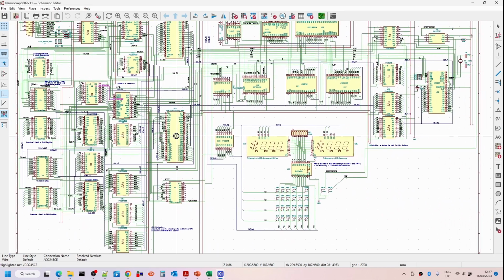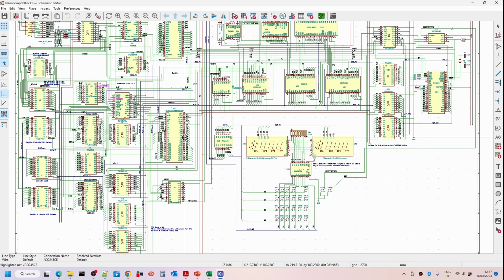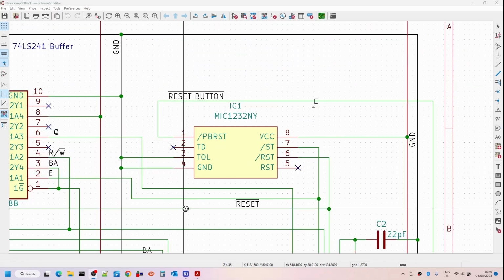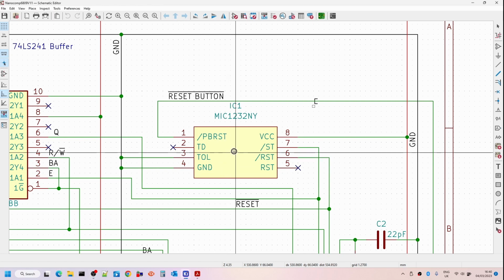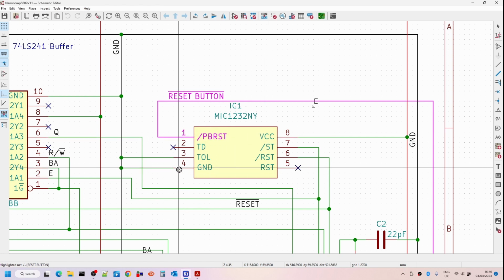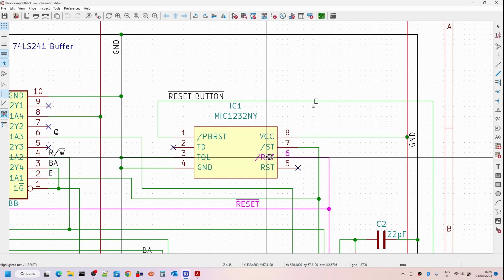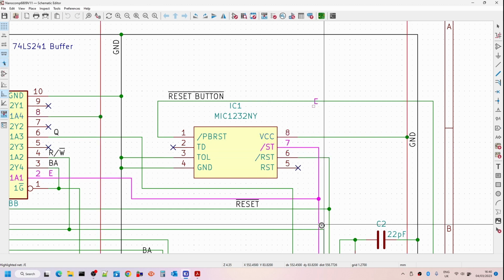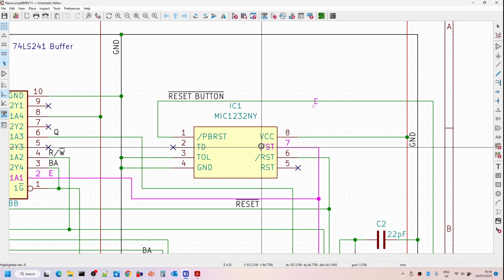So those are the changes. What I'm going to do now is to go in and look at the board layout and the wiring of this up, and then we'll come back and look at the software that we need to drive this. We're first going to install the microprocessor, power supervisor and reset chip. So this chip here, you can see on the schematic, takes the reset button. It's got ground signals, VCC plus 5 volts, and the output is the low reset, and we also need to feed in a signal from the microprocessor to prevent it from being reset due to the watchdog timer.